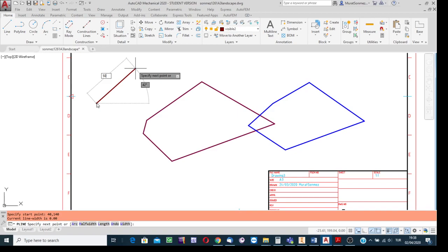But here no need, because while the dynamic input button is on, to teach the software that 50 is not the length but the delta x value, not relative to the absolute origin but relative to the first point, the starting point, I simply clicked on the comma key.